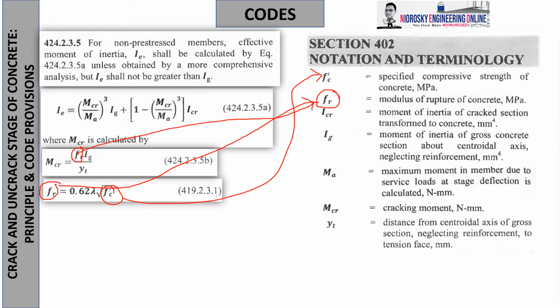Now, mark in violet, the I critical, I sub CR. So, this will actually be used in understanding stresses. Okay? So, ICR can be IG and ICR cannot be IG, dependent on the situation. IG represents the moment of inertia of that particular axis in centroidal, neglecting, take note, neglecting reinforcement.